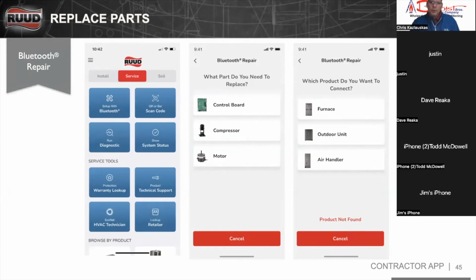Well, in the EcoNet, we don't ever want to just wire a condensate drain safety to kill power to the EcoNet. So we use the auxiliaries and we name those and put those in, and that gives us alarms or gives us functions, instead of just killing the EcoNet system like we would normally do with the traditional system. Justin, what do you have in mind?